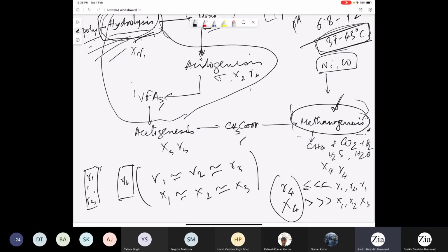So to avoid inhibition of methanogenesis, you just separate them into two reactors. The first reactor will be a little bit smaller because you do not need to handle too much solid material to get a certain amount of acid, which can be handled by a bigger methanogenic reactor. When you separate them, you have good control on the acid flow to the methanogenic reactor. Whatever amount of acid can be utilized by the methanogenesis, you just add that much.